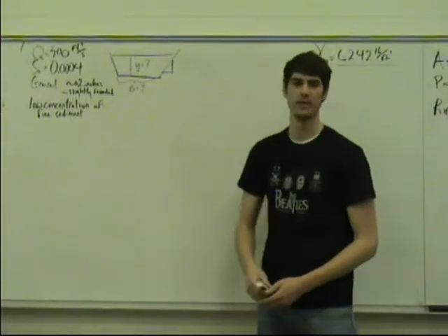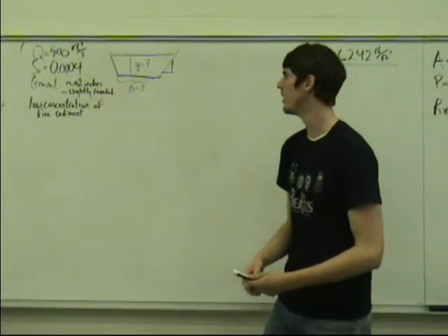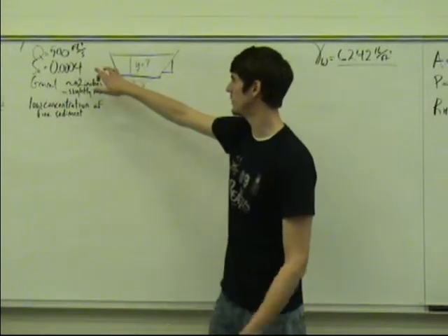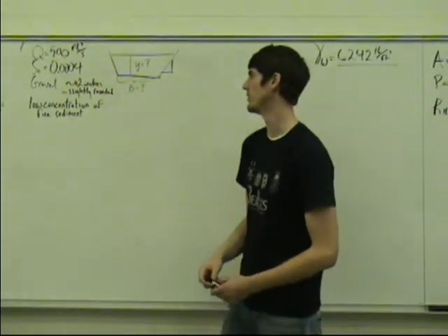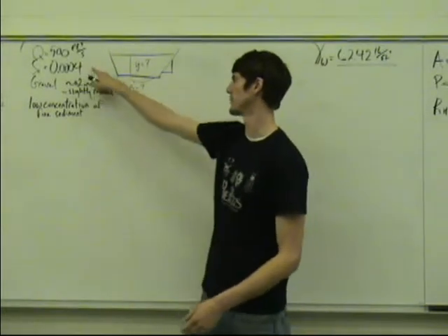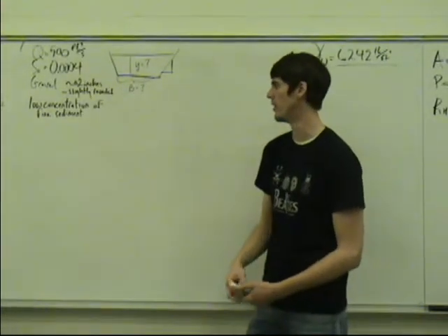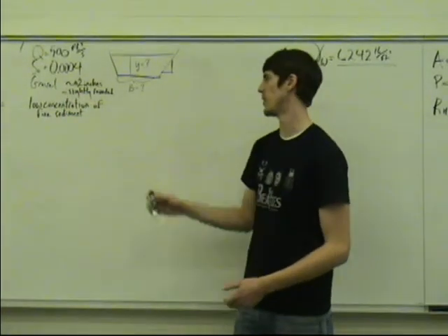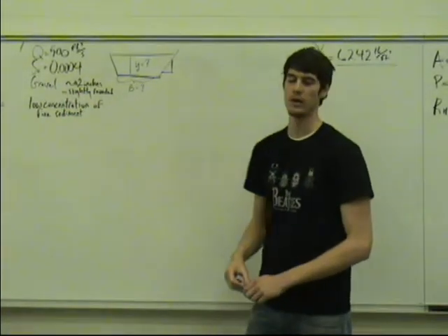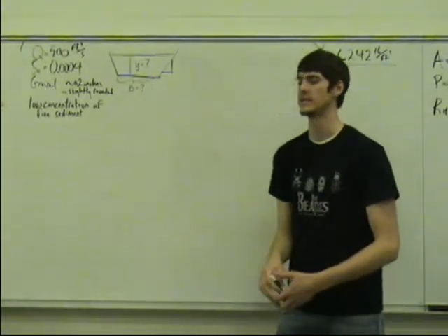Now we're going to try to solve a problem using the drag force method. Given in the problem statement, we know that the design discharge that we're trying to design a channel for is 500 cubic feet per second. The bottom slope is going to be 0.0004. We know that we're designing it with gravel with a particle size of about 2 inches that's slightly rounded. We know that the water's got a low concentration of fine sediment.